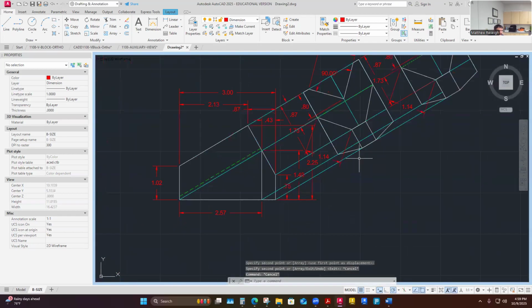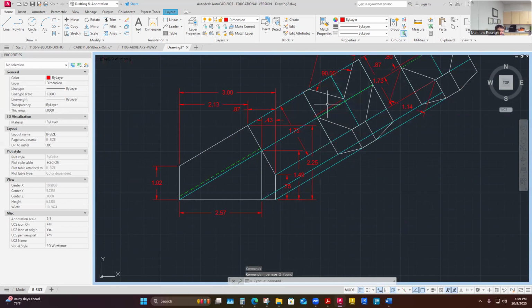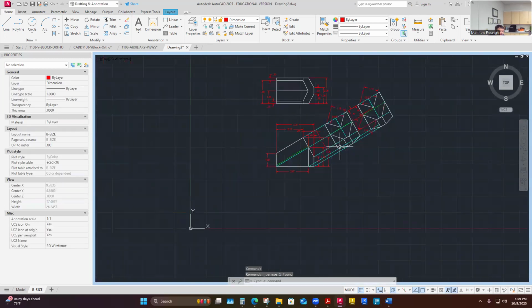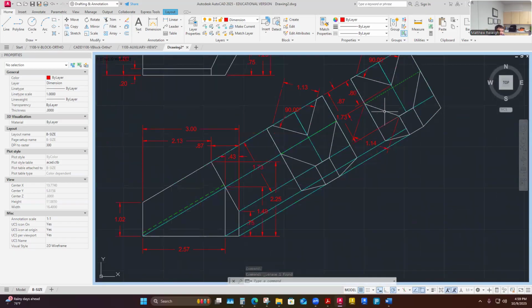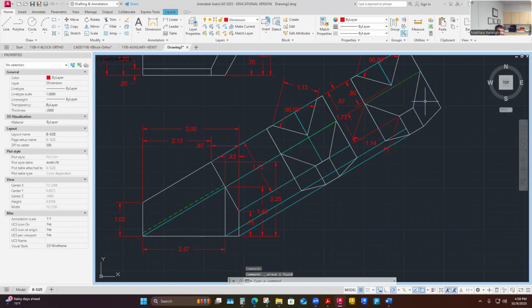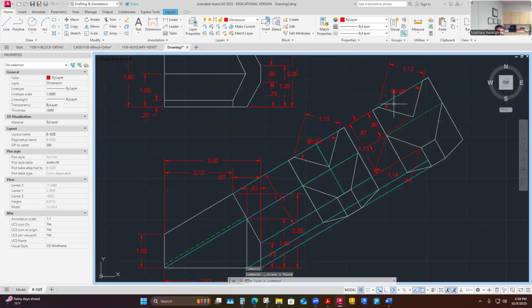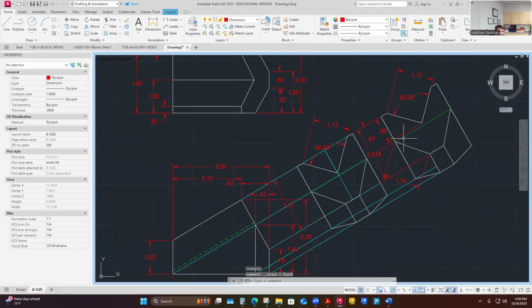And so when I copy that, it allows me to get rid of these that are interfering with my other viewports, and I can get rid of a lot of them actually. So I can get rid of that. I think that's got everything that I needed. I ended up taking some construction data with me because I had that layer on. I really didn't want that to come with me. I could have deselected those, but I'll just delete them right now because that's redundant construction.